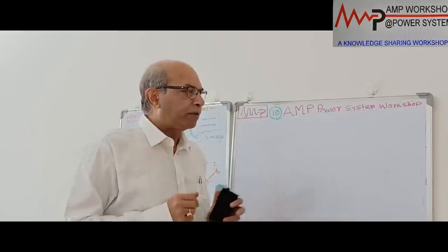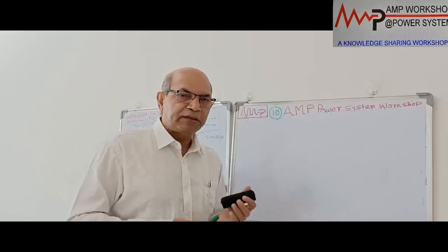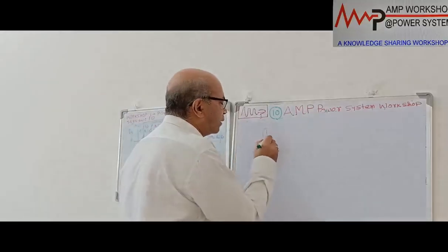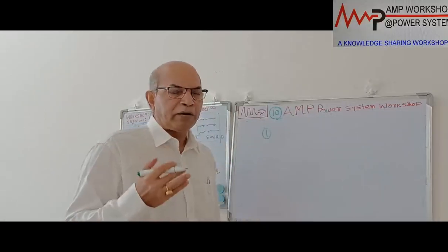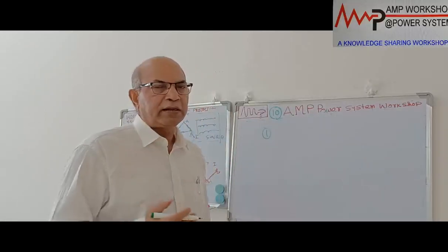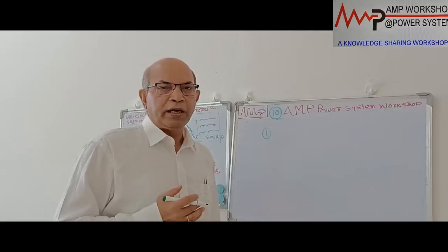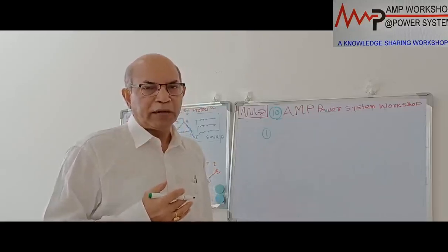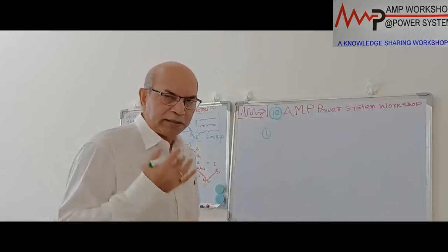That we'll calculate afterwards. Now, as it is an oil filled transformer, as we have discussed during transformer protection, this oil filled transformer has its own various electromechanical devices which can take care of all the minor faults inside the transformer: interturn fault, phase-to-phase fault inside the winding, or earth fault in the winding, or other types of insignificant fault taking place inside the winding, if some current material inside, if there is a flashover inside the winding.